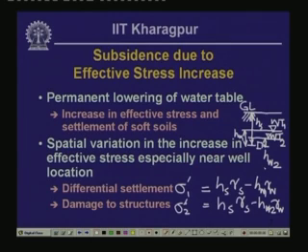So the increase of effective stress is going to be non-uniform depending on the distance from the water well, and this is going to trigger differential settlement within any facility constructed within the zone of influence of the water well, and differential settlement is highly detrimental to the performance of structures, and it could actually damage them.